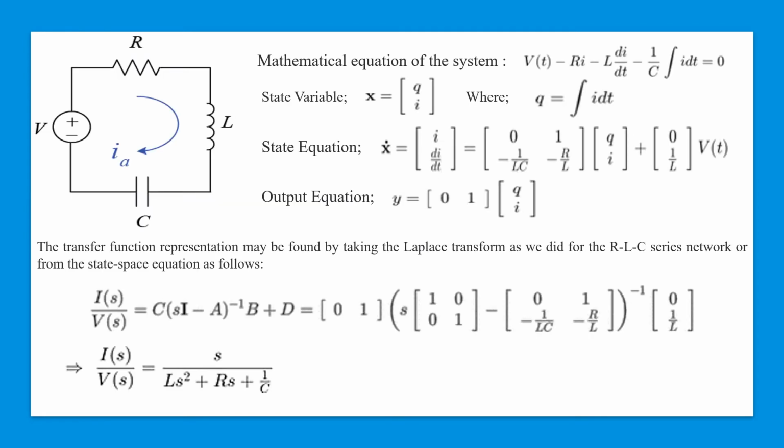Electrical networks. An electrical network is basically a combination of resistor, inductor, capacitor, these three circuit elements, and the source. The source may be a voltage source or current source. With these components we can make the circuit in two ways: one is a series circuit and another is a parallel circuit. In this figure we are considering our RLC series circuit, where the voltage source is V, a DC voltage source, and the current throughout the circuit is supposed to be i.